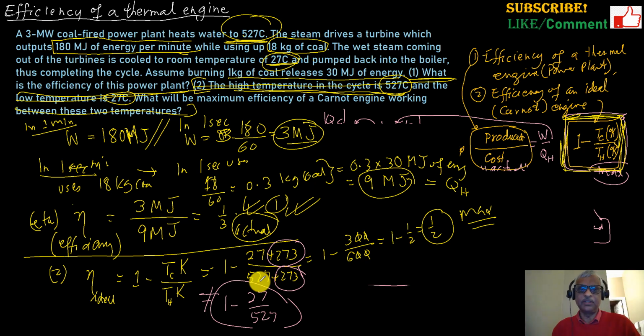There is a similar type of efficiency in a reverse way. For instance, when you're trying to cool something, and that's called a refrigerator. In a refrigerator, you can also ask what the coefficient of performance is. The efficiency is called coefficient of performance. It means that in a refrigerator, you want the energy that you use up to be the least amount, right? So your cost is not like QH, your cost is the W, the work you have to do, the electricity that you have to supply. While the efficiency will always be less than or equal to 1, the coefficient of performance will be greater than 1, and so you want the highest coefficient of performance. Maybe I'll do a video about the refrigerator, okay?